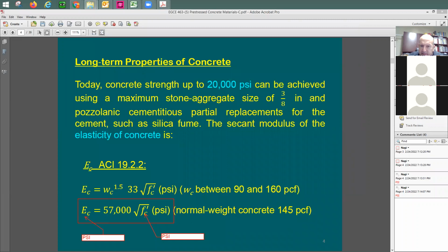Professor? Yes. The concrete strength that you wanted was 5,500 at 28 days. Yes. The average strength was almost 7,000 at 28 days. Was that okay? Yeah. Okay. So this is going to be okay because I'm looking for a stronger concrete, so it should be fine. Okay. Is there a range you don't want to go over? No, this only matters when you have special testing, or you're doing